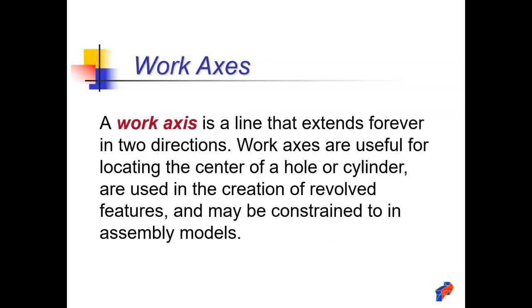An axis is a line that extends forever in any two directions. Work axes are useful for locating the center of a hole, or a cylinder, or anything that can be revolved, anything that you see like a cup or a lamp, or anything that is symmetrical and round that may have been turned on a lathe or extruded in that fashion. Revolving around that work axis is the best way to create that point.